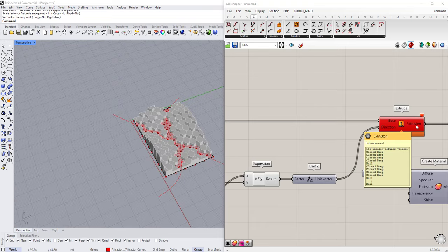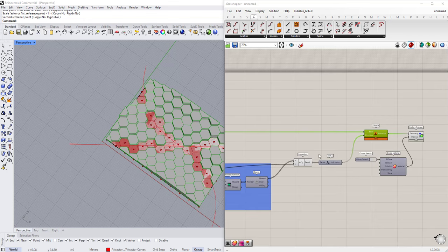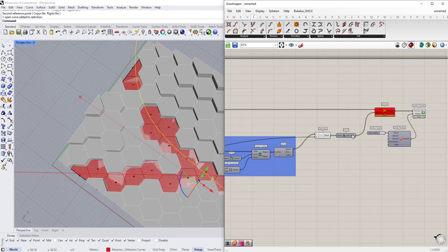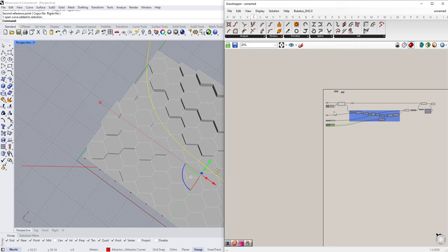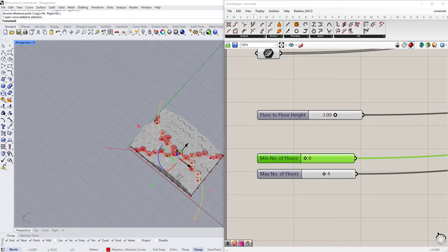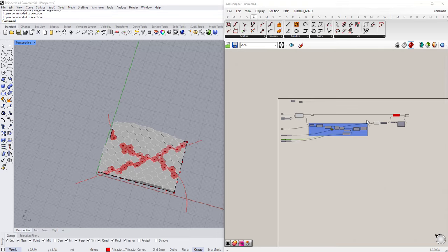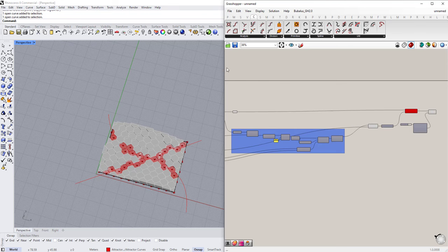And as you can see, when the value is 0, the extrusion is 0. This is why it cannot extrude some surfaces, because the value of the extrusion is 0 actually. If we change this maybe to 1, this error will disappear. But as you can see, I want some parts, some gaps, or some passes like this. So let's keep it. And we are done with the script, but we can start refining the script a little bit more to add more details.